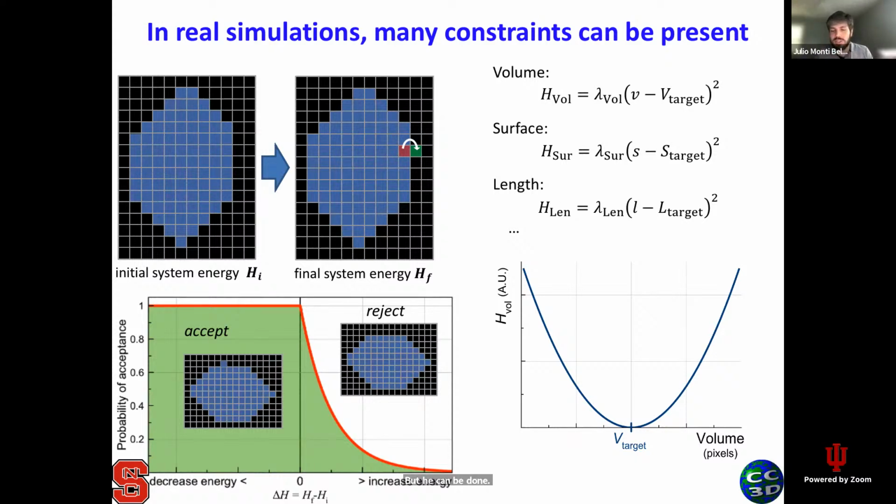Yasmin, I just had a question here. Is there a way to incorporate gravitational forces into a model? Yes, there is. You can add them directly by just adding a constant force on all your cell compartments pointing down, okay? So that's a way to add the gravitational forces.